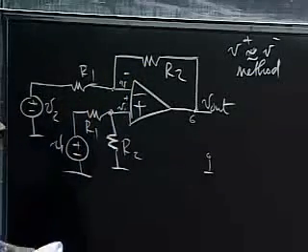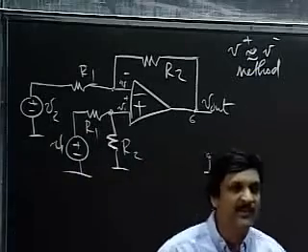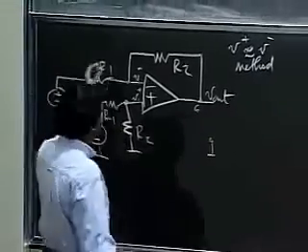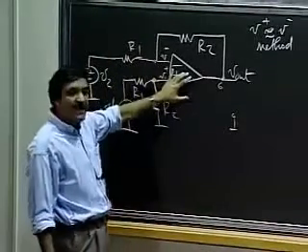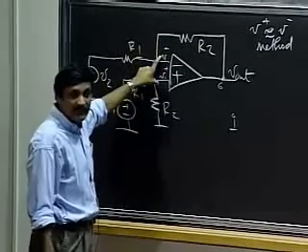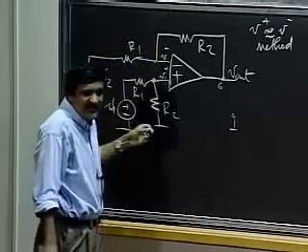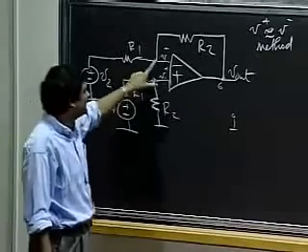and tend to make these two equal. So being rather tricky here, what we'll say is, look, if we know for a fact that under negative feedback the op-amp is going to engineer these two node voltages to be more or less equal, then why don't I just use that fact to begin with and analyze my circuit assuming that is true?